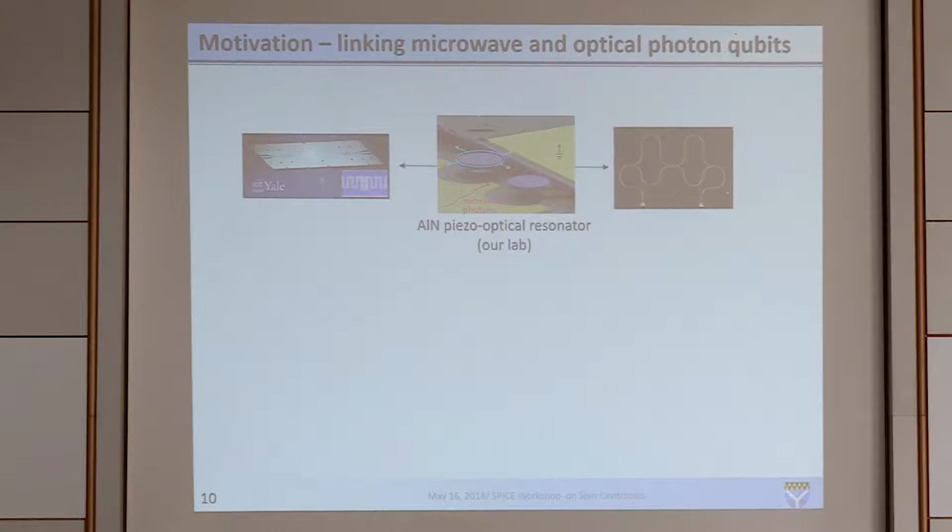And that mechanical resonator is on the order of a megahertz. And in my lab, we also work on mechanical resonators at around 10 gigahertz to start with. It's a tiny, tiny disk about 6 microns in diameter, made of a piezoelectric material. Through Chi1 coupling to the microwave and Chi2 coupling to the optics, you do the conversion. This also promises to be a very nice converter because the mechanical resonator works at 10 gigahertz, at the dilution refrigerator temperature, in the ground state. So there's no noise added to the system.